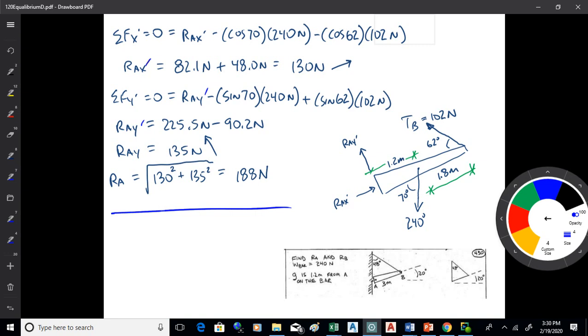So we okay with that? So just a little trick there. Sometimes if you've got something on an incline, if it's at an angle, just reorient your axes. Okay? Now you can always use the original method I showed you. It's just sometimes a little bit more work. You could have done this one with a standard XY coordinate system too. You would have had to do a little bit of calculations there to find moment arms. That would have involved trig, and it would have got just a little bit more complicated, that's all. Okay. So are we good with that? We got any questions on that?